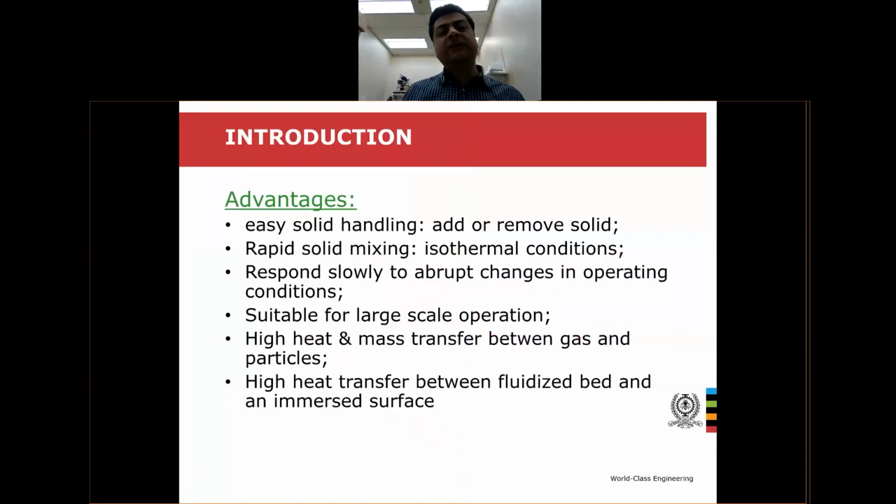But definitely there are advantages with fluidization, especially because of the solid handling. It's very easy to add and remove solids. You will have rapid solid mixing, so you can maintain a kind of isothermal condition. But the most important advantage of fluidization is the really high heat and mass transfer rate between gas and particles. And this is the most important advantage of fluidization. So you will use less energy, for example, because the heat transfer coefficient is quite high in fluidization.